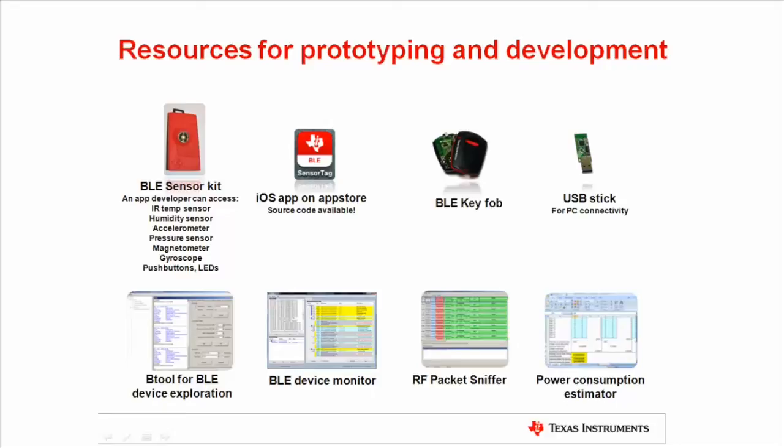The USB dongle can be used together with our powerful PC application, BTool. BTool provides complete control of a connected network processor via a graphical user interface. It allows a developer to test every aspect of the Bluetooth Low Energy stack. The BLE Device Monitor is a Windows application that displays all services and characteristics on any Bluetooth connected low energy device. It can also be used to read and write to the exposed characteristics.